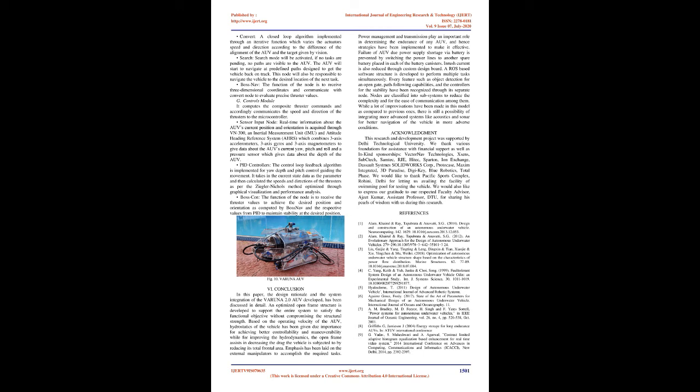Fig. 9. Software stack. Software module. It processes the image input through two cameras, front and bottom, to generate guide data according to the task planner. The package supervises the following nodes. Image processing nodes, pre-processing techniques. Several image processing algorithms like CLAHE and Gaussian blur are implemented to overcome issues like poor visibility, turbidity, etc.